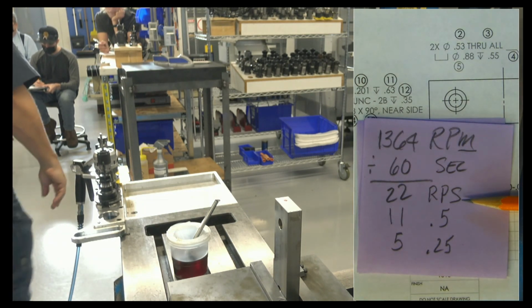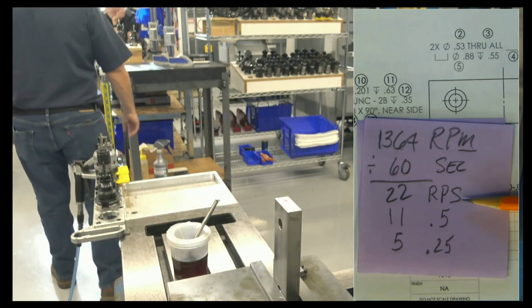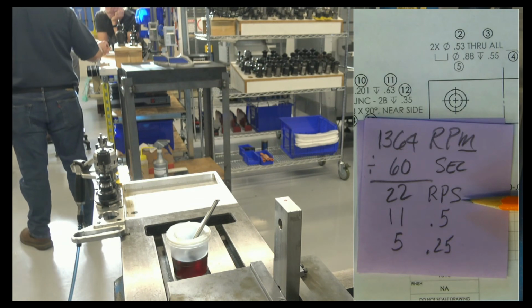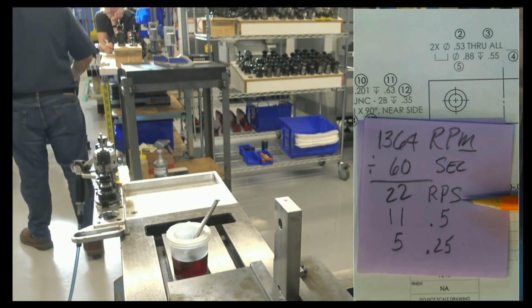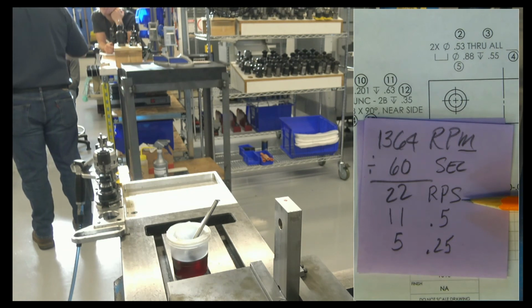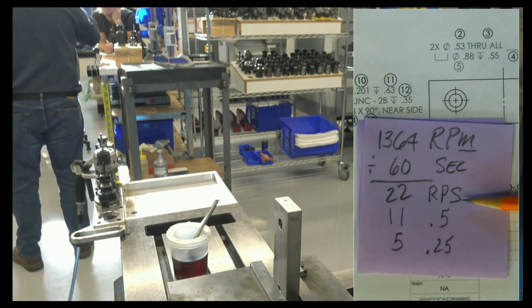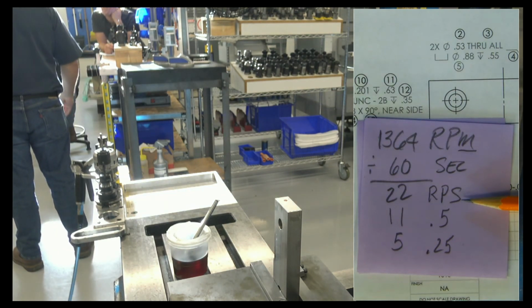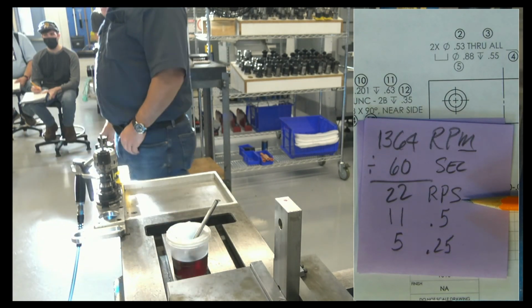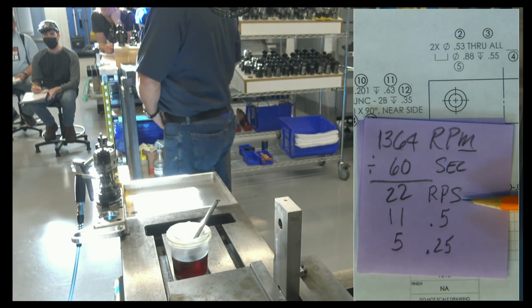Do I want that? No, you want 1 revolution. Okay, well, what's wrong with 22? Too many. Okay, that's good. Anybody put a point on that, why it's too many? What's it going to happen? Heat up your tool. It's going to create heat. That's all it's going to do. Once it does 1 revolution, I'm creating heat. So let's not do 1 second. So I want to dwell for 1 revolution.